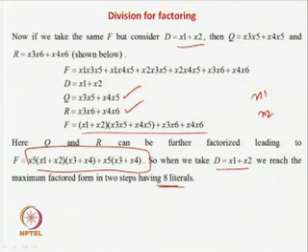In this case, x1 is in 2 places, x3 is in 3 different places, x5 is in 5 cubes, and similarly x6 is in 1. So you can say that I will take x5 as a divisor, because x5 is appearing over here, over here, over here, and over here. So if I take that x5, then I am going to get x1 x3 plus x1 x4 plus x2 x3 plus x2 x4 and so forth.